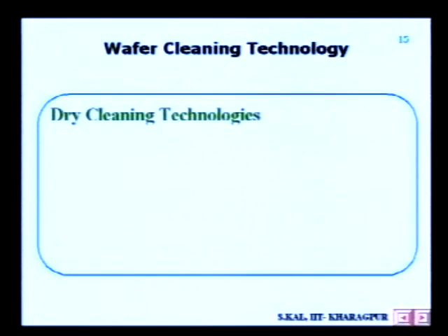Among the different problems in the wet cleaning process, some are particle generation, drying difficulties, cost, chemical waste disposal, incompatibility with advanced concepts in integrated processing, and general inflexibility. The dry cleaning process may provide a way to solve these problems, although currently it is not completely useful.